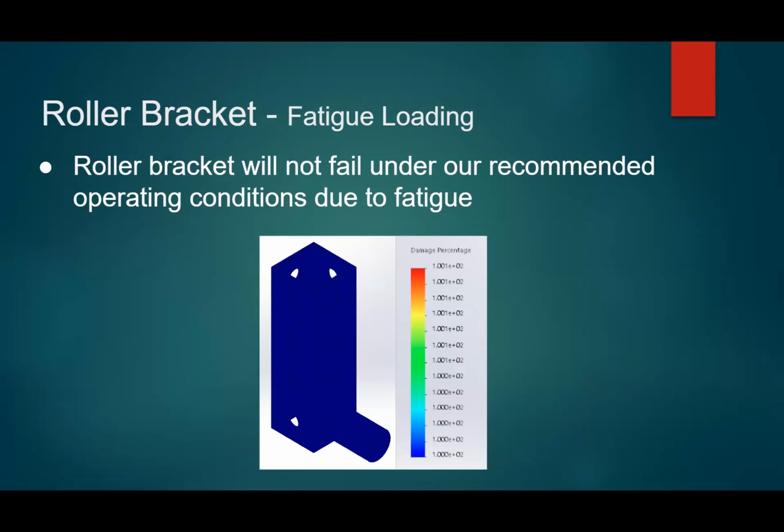Next slide. This is that same loading scenario, but in fatigue, because again, the roller bracket will be undergoing a fluctuating force due to bumps in the road. And we're rated at over 1 million cycles, or infinite life. Next slide.